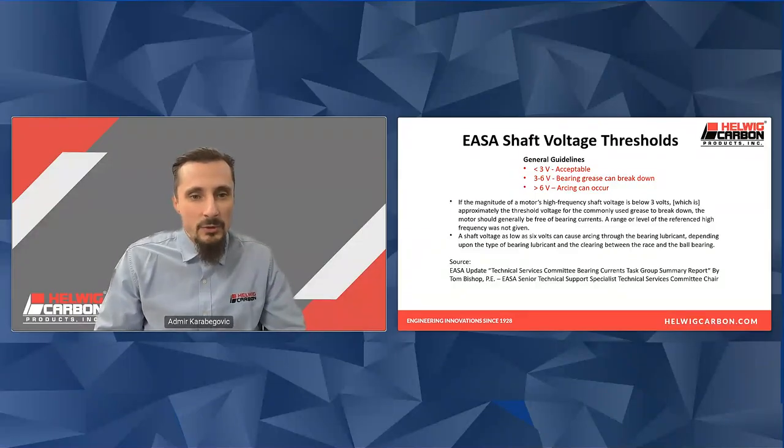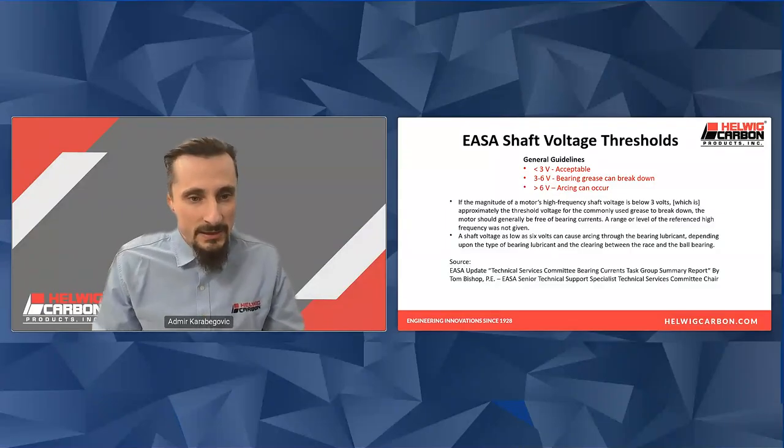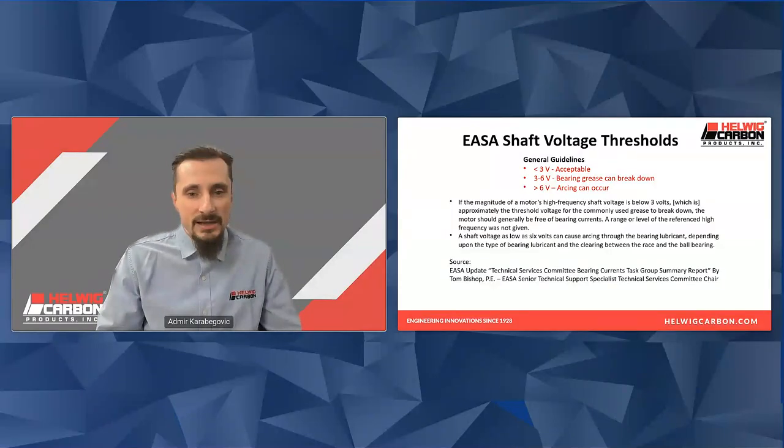If the magnitude of a motor's high frequency shaft voltage is below 3 volts, which is approximately the threshold for commonly used grease to break down, the motor should generally be free of bearing currents. A range or level of the referenced high frequency voltage depends on the type of bearing lubricant and the clearance between the race and ball bearing. The source is the ESA Update Technical Service Committee Bearing Currents Task Group Summary Report by Tom Bishop.